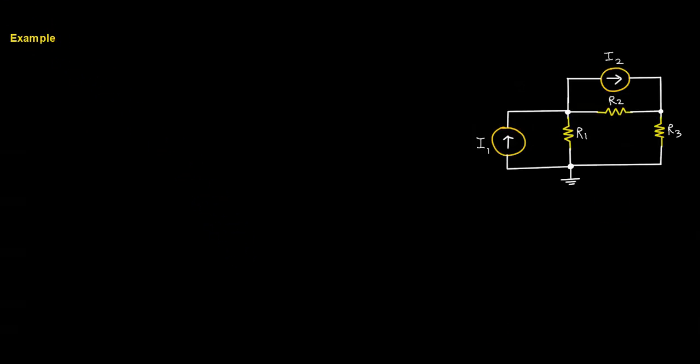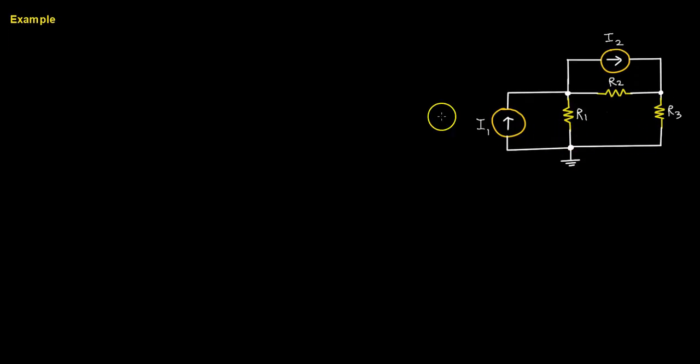Okay, now let's go ahead and work on a more interesting example and apply all of the techniques we've learned thus far and the points that we learned about nodal analysis, which is to first select a reference node and find the remaining voltages and solve for those voltages or currents. In this case, we care about voltages that are unknown at these two individual nodes, and what we're going to do is apply KCL in a very methodical manner, which is called nodal analysis. And if you watch lecture 9, the expectation is that you will choose your favorite matrix method to solve the equations that arise from this system.